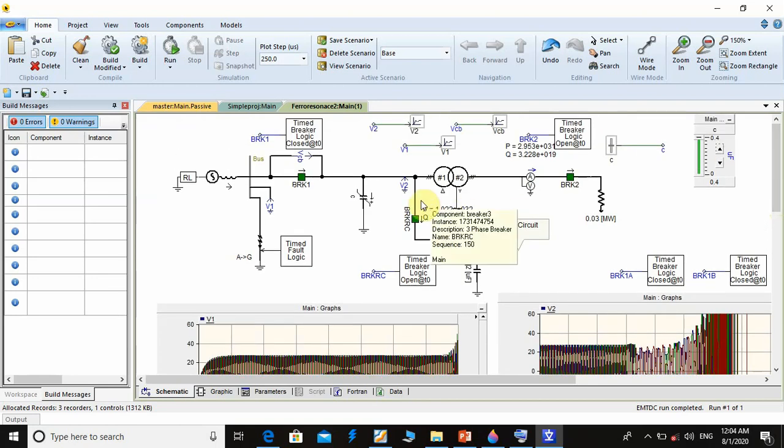So that means we should not de-energize an unloaded transformer with a long cable, because when the transformer de-energizes, there is energy trapped from stray capacitance with the transformer. That means there is oscillation, but I think this oscillation damps very quickly, especially if we have resistance.